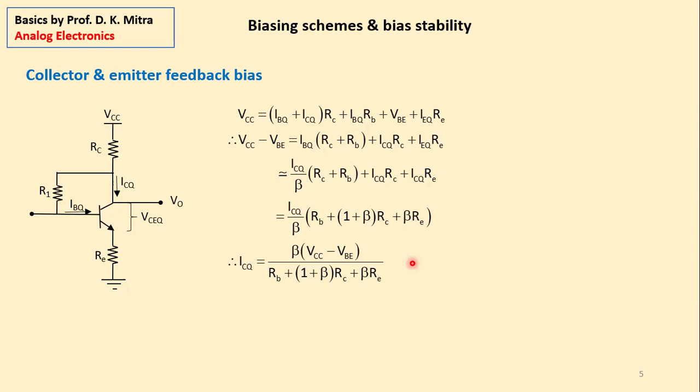That is because the biasing points of the various transistors change a little bit here and there; there will be multiple transistors in a radio amplifier. That is called bias instability. Next day, we shall see how we measure bias instability, how we take care of it, and what the remedy is.